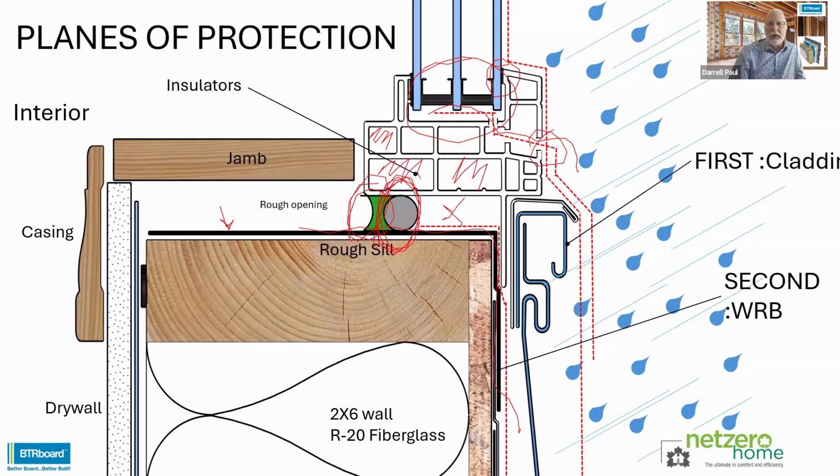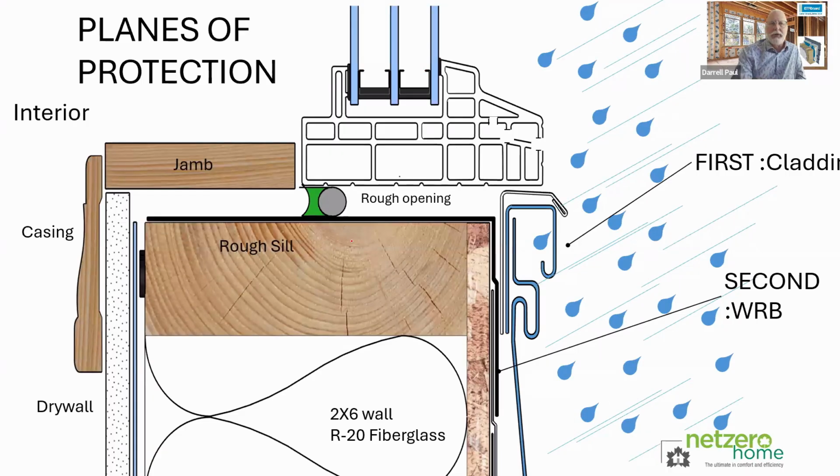So whether we're putting in a flange window or whether we're using, say, a non-flange window, a box window like you see here, the direction of the water flow is going to be from the outside when the rain hits. It's going to also be from that cavity that's underneath the glazed units, and then also from the rough opening. And we're taking any water that gets in there when we're dumping it back outside.